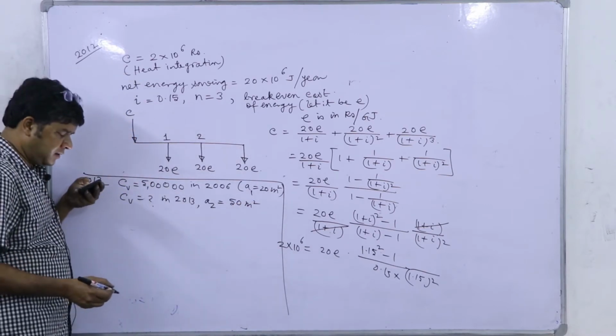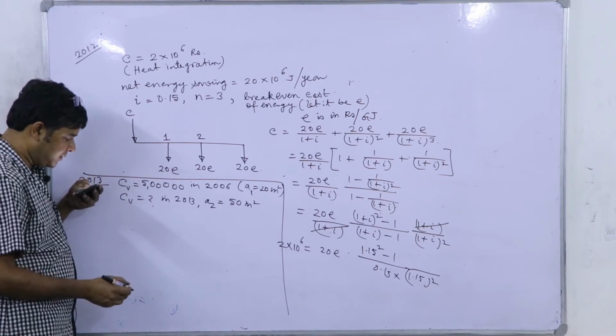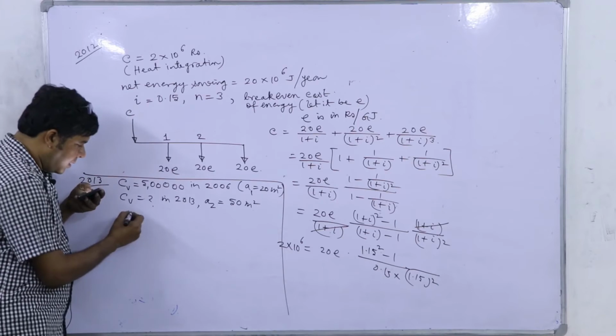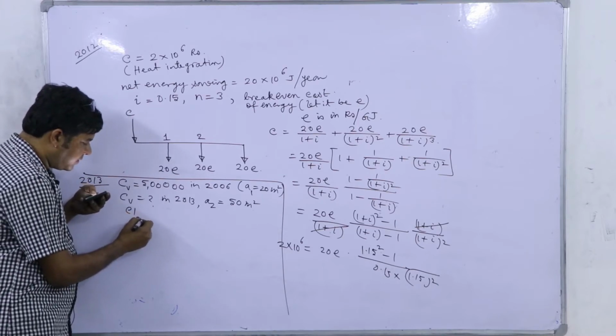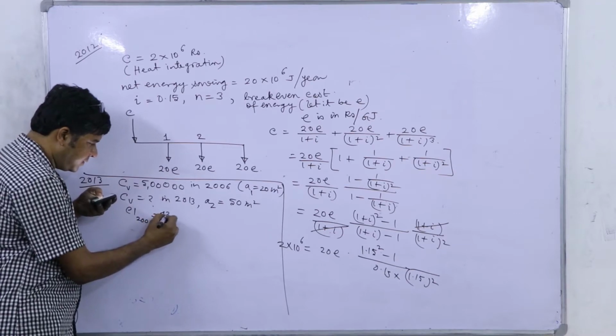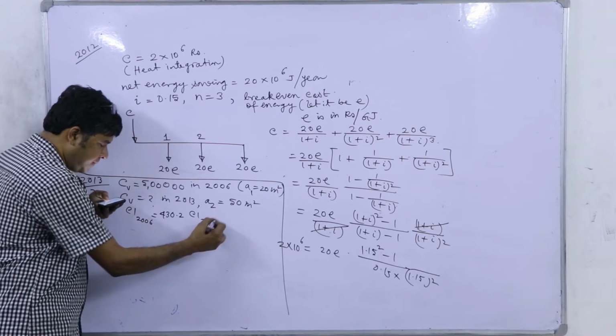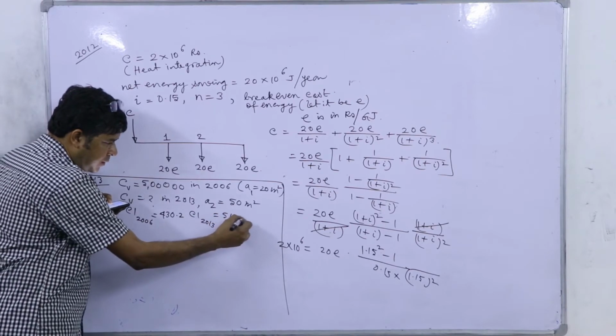Assume the 6/10 power rule, the factor rule for scaling, and the cost index of 2006 is 430.2, and the cost index in 2013 is 512.6.